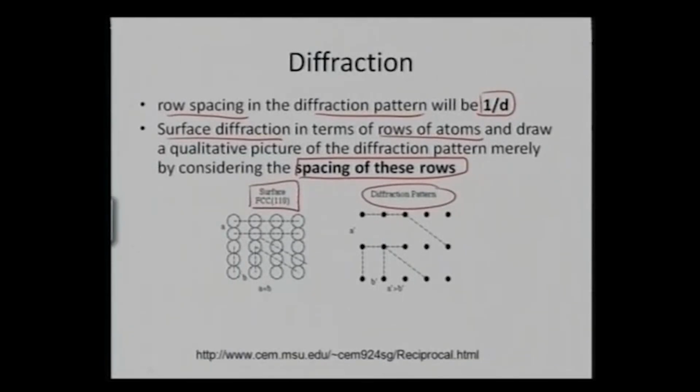So if I had a real space like this, where I have say for surface of FCC 110 plane, then I can see that in my FCC 100 plane, it becomes more like this. I have atoms which are associated at this particular location, as well on the face centers. So I have something on the faces as well. So I can get something more like this, and seeing this particular 100 plane, I can see that I have planes which are more like this.